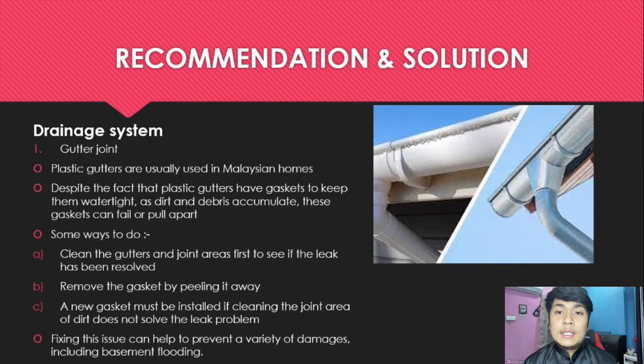First, clean the gutter and joints area. Second, remove the gasket by peeling it away. Third, make sure there is no dirt if you want to replace the gasket with a new one. Fixing this problem can prevent a variety of damage.